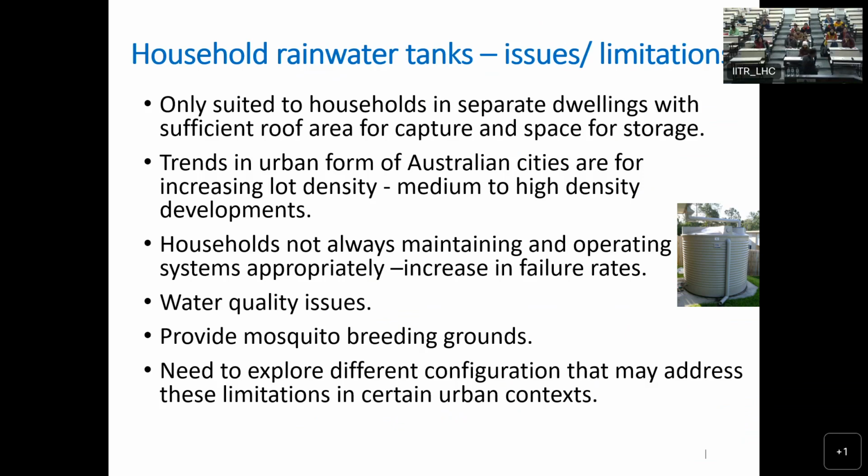So what I was talking about was that with different sizes of rainwater tank, for example 5, 10, 15, 20, 25, the volumetric reliability, that is the ratio between what is available and what is the demand, will be different.